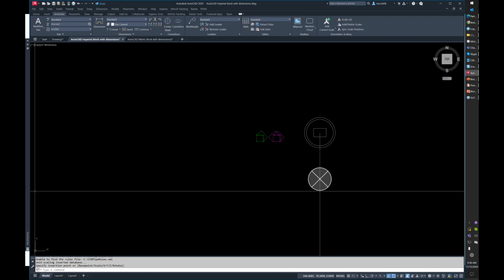If you're getting drawings in from outside and they are not using MicroStation or AutoCAD, or an AutoCAD clone like BricsCAD, some of the others, if they're using one of the obscure ones, what is it? It's TurboCAD. There's another one that they use over in Europe quite extensively. How they handle blocks is different. When you open up their drawing, all of their block definitions are done as groups, and every block has its own name. Their drawings are ginormous, and it requires some effort to clean that up and get that fixed.